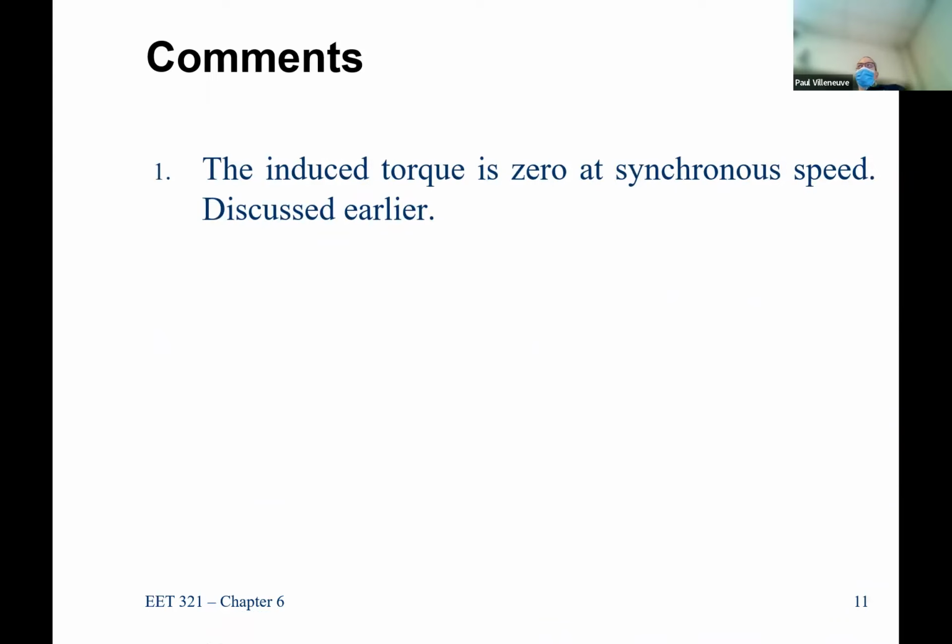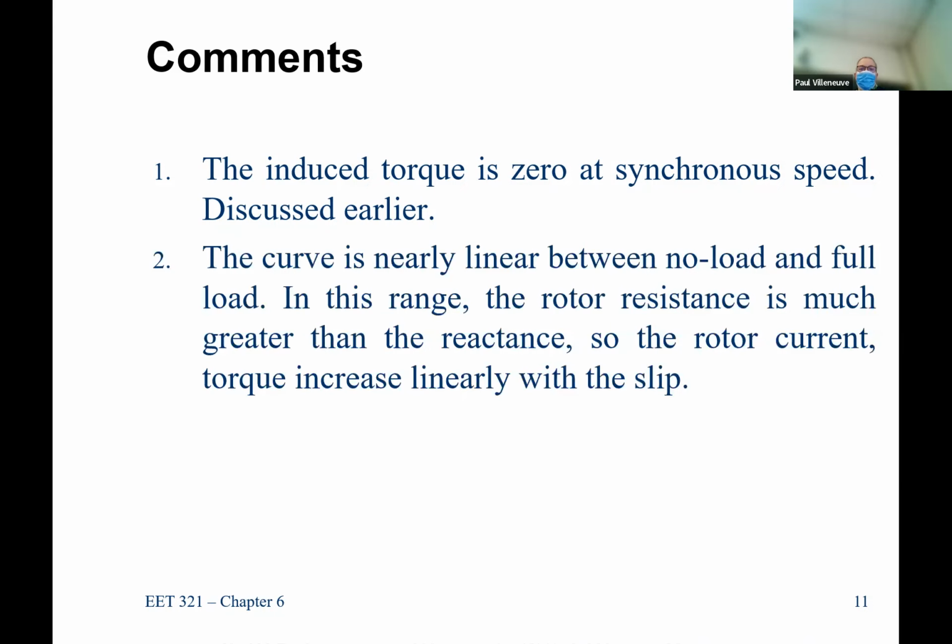So we talked a little bit about this in lab, but there's no torque when you're at synchronous speed. And the reason is we have no dφ/dt when the rotor and the stator field are spinning at the same speed. That's the mechanical rotor and the electric field on the stator. They spin at the same speed, so there's no dφ/dt.